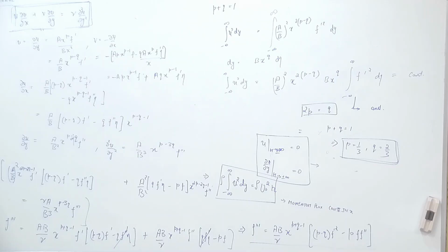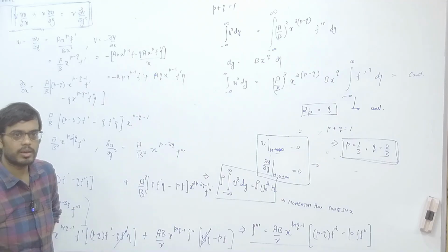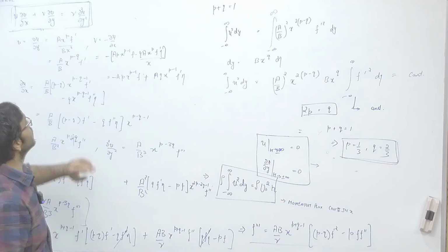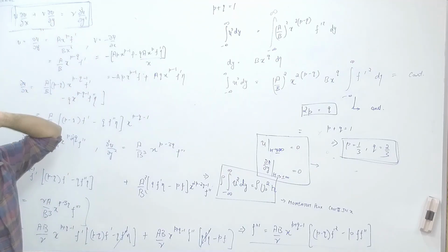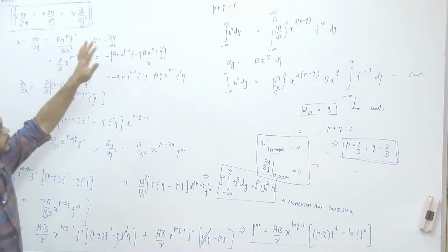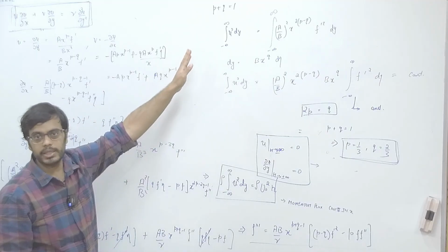Now, where was the jet specific part here? Where was the jet specific condition that we applied? This equation, as we know, is applicable to zero pressure gradient boundary layer as well. So p plus q equals 1 is not really a jet specific condition that you have obtained.